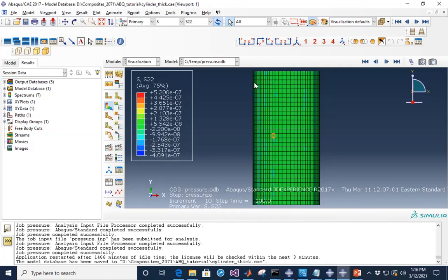which is what we would expect because there are no longer any constraints in the vertical direction. Because it's unrestrained, we've not imposed constraints on the top face, so we have allowed it to expand. The top face itself is traction free, and that's why we see the vertical stresses are in fact quite close to 0.